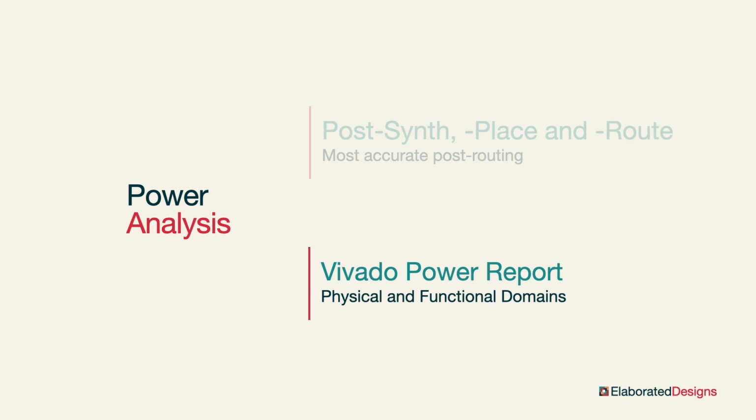The power report tool analyzes the power requirements of our design using information from the physical domain and the functional domain. Information from the physical domain includes the power supplies, the thermal power dissipation system, the enclosure, and the properties of the printed circuit board. This information is usually provided by the electronics and mechanics engineers.